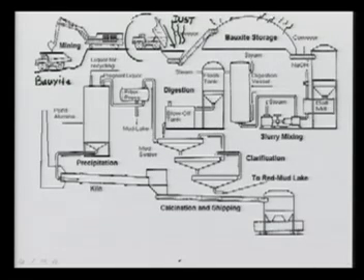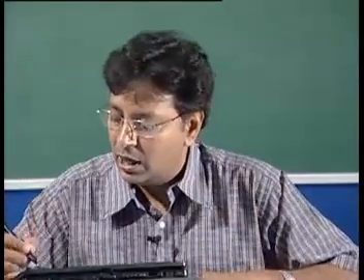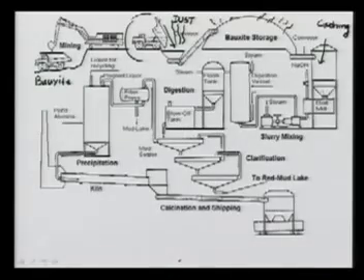Finally it comes to the ball mill, as you can see here. What we are really doing in the ball mill is crushing. We are trying to crush the bauxite, I won't call it fine, to about 100 micron size, so that we can do the further processing of the bauxite. And after the ball mill, once it is opened, this can also be a source of emissions.